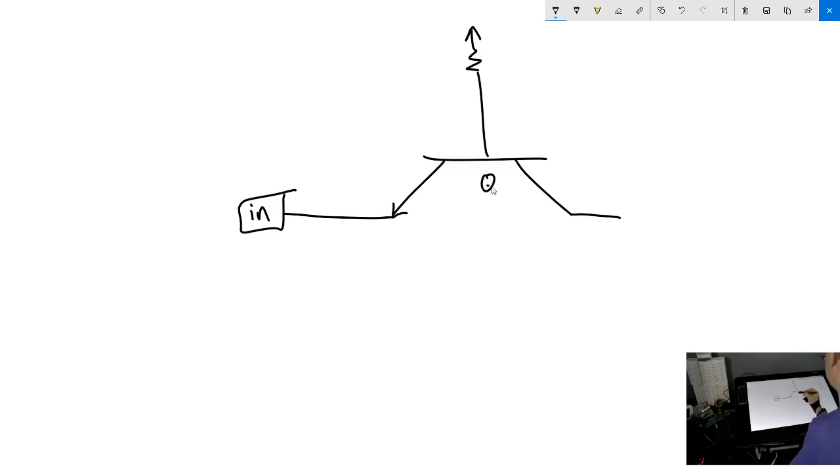So there's an input transistor. And rather than talking about why this transistor looks like that, I'll just say that this is an input, and basically, this is sort of like the inverse of the input. The signal right over here is the inverse of the input. Typically what you'll see is a diode, and this is a reverse bias diode, so it's a protection against negative voltages, because if you put a negative voltage on the input, then current is going to flow through that diode. More often than not, destroying the diode, but at least it doesn't destroy the rest of the chips.